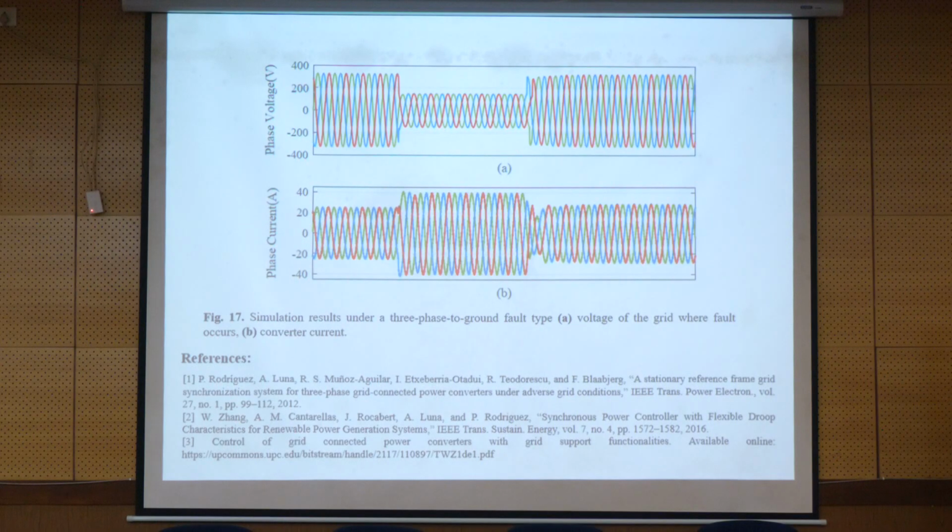So now this is an example of the system, so you know how we can actually provide the injection from the three-phase system to single phase. We see that we have the voltage sag here, and then we provide an increment in the value of the current, which basically provides the active and reactive power for the grid to compensate the voltage here, so more reactive power compensates the voltage drop in the power grid.